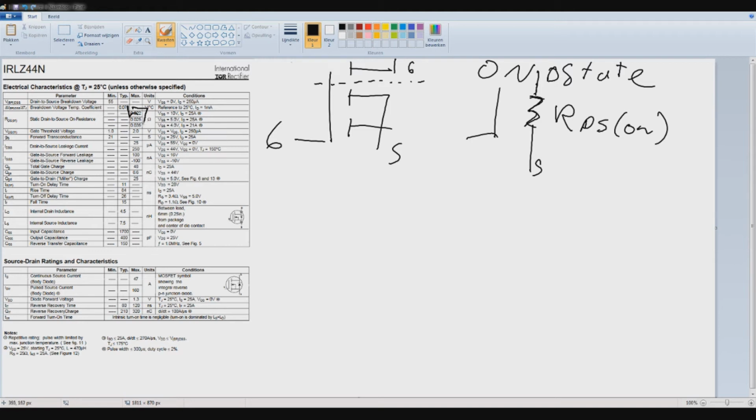And as you can see, if you apply a higher voltage to the gate, you will have a lower resistance. Therefore it's ideal to have a voltage that's approaching the maximum, but we'll take a look at it later at the graph, which shows ideal gate source voltages, and you see it is lower.